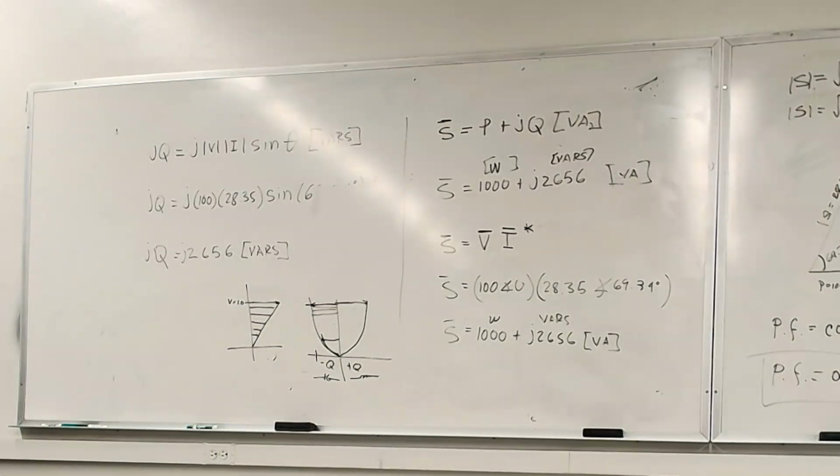The synchronous machine is a dog because if there is a fire, the dog makes sure that you get out of the house safe before the dog gets out. They're very loyal. A synchronous machine, they're very loyal. The voltage is creeping down, and they keep on pushing vars. They keep on trying to help you with the voltage and the power factor. Okay? But as he said, the challenge is that they're very expensive.